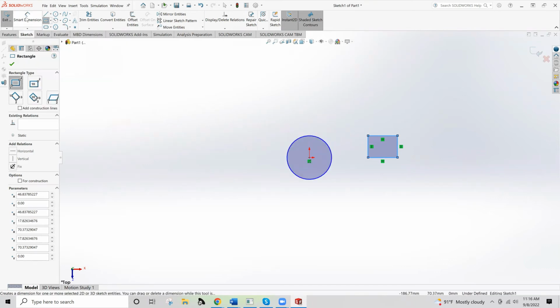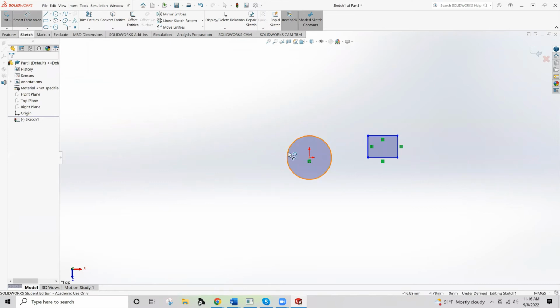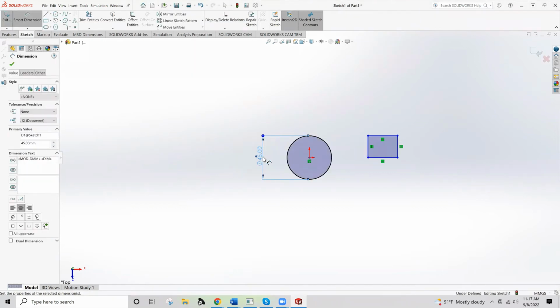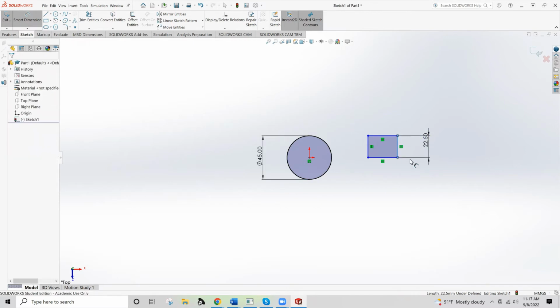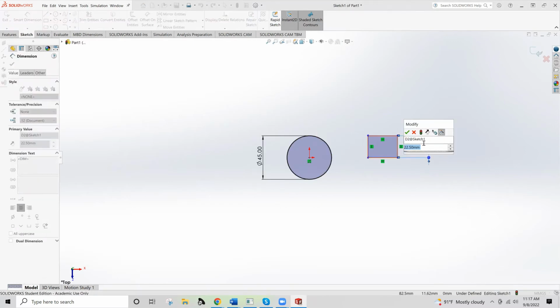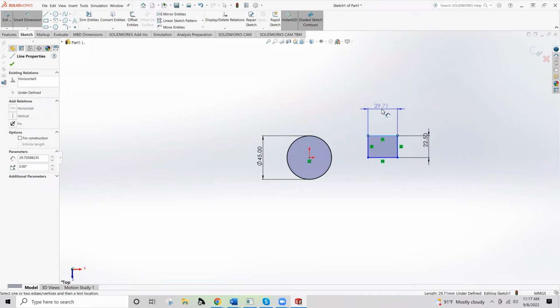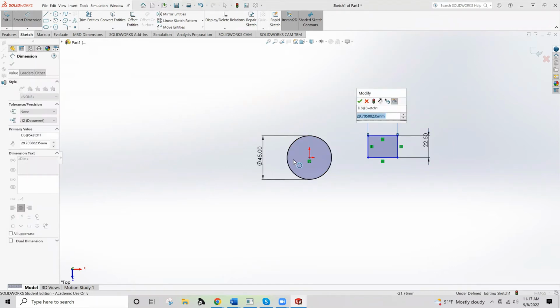And when we go to start doing smart dimensions, which is one of the things that we start doing immediately, we say, actually, this needed to be 45 millimeter. Now what this has done is, because of that referencing, this has become half of that, which is our 22.5 millimeters. So the smart dimensions allow us to change a sketch from blue to black. Anyone remember what blue to black change means for a sketch?